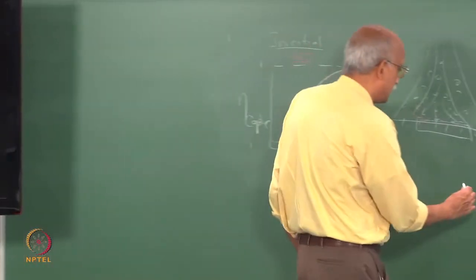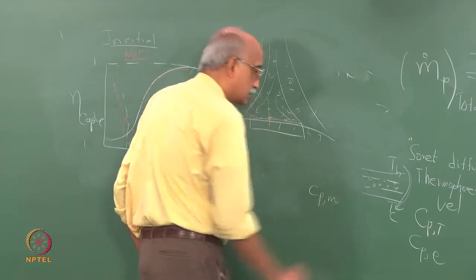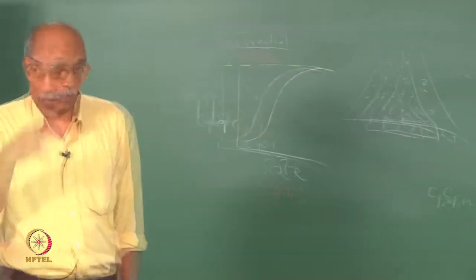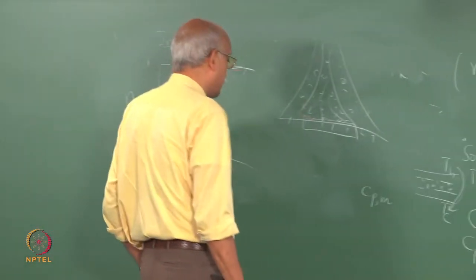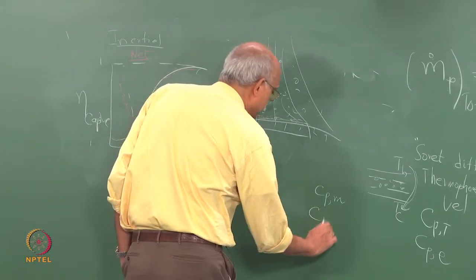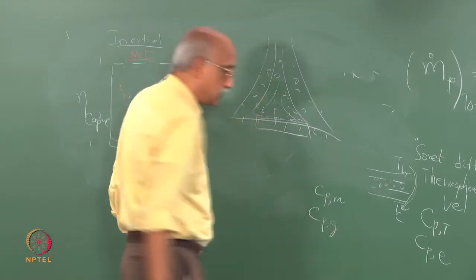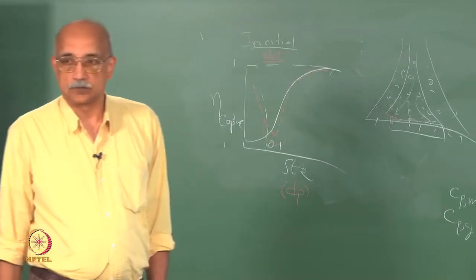And of course, there can be a magnetic gradient. If you have magnetic particles flowing in a suspension and you apply a magnetic field across the flow, you get a magnetic phoretic velocity. You can even have gravity, which can actually be looked at as a phoretic velocity also.